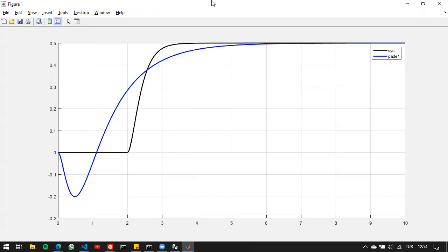If we apply an input to a transfer function, it will respond at 0 because it has no delay. But if we have this inverse or this undershoot here, then we will cross back here to 0, and then we will rise to the response or to the DC gain here. So we're kind of using this zero that we've placed on the right half plane because it will result in undershoot, and the time that is wasted here should somehow model the delay here. So that's kind of the strategy.